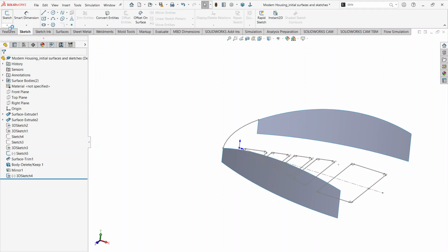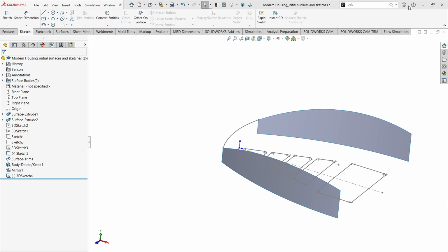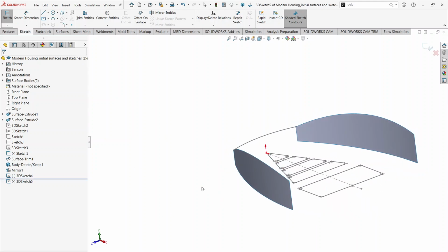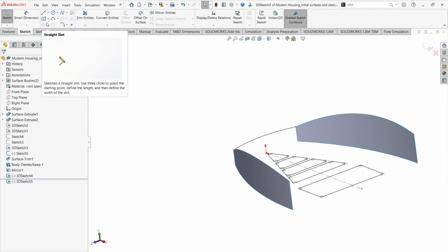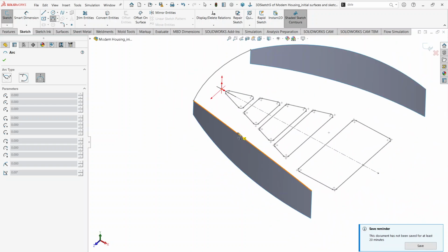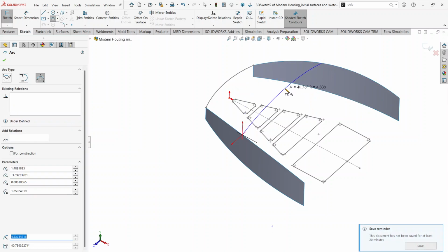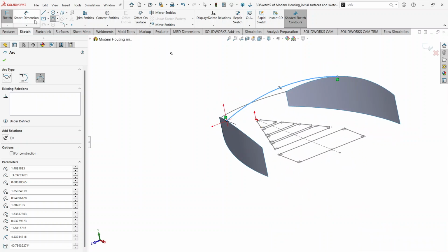And then I will start the second sketch. For the second curve, it's in a perpendicular plane with a radius of 8. So I will start another 3D sketch. If I want it to be in a perpendicular plane, sort of on top of it, it would be in a YZ plane. So I would select my 3-point arc, but this one I'm going to tab to the YZ plane. I will start from any point here and add it here, and then I will dimension it later. So if I go to smart dimension, the radius of this arc would be 8.